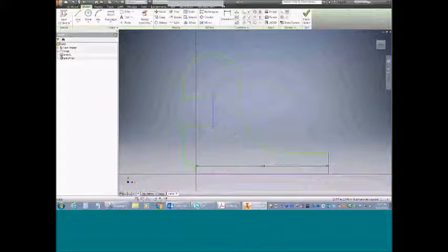And the constraints are really there because they're parametric, and it's a great way to produce geometry, but you get to describe to the software the design intent of this part. We don't know what this part does, but if this surface has to always be the same as this surface, because it has to do with the function of this part, then I need to make sure I build that in with constraints, so that no matter how somebody else edits this, I will always maintain that design intent.